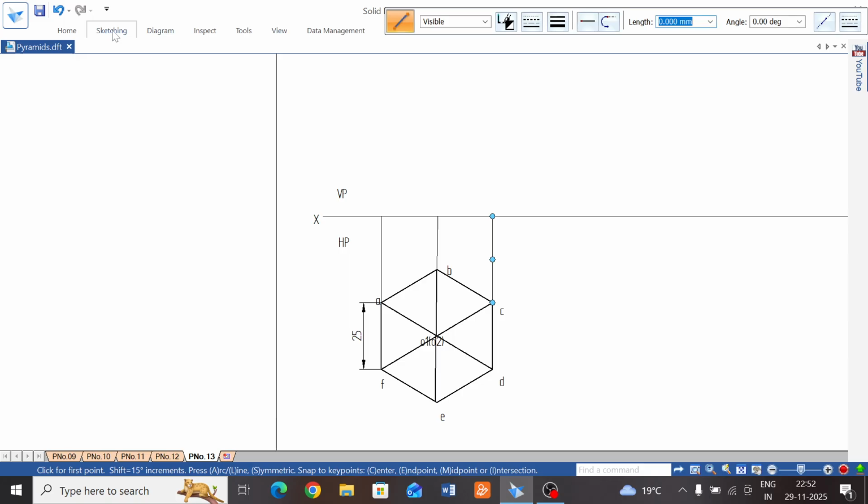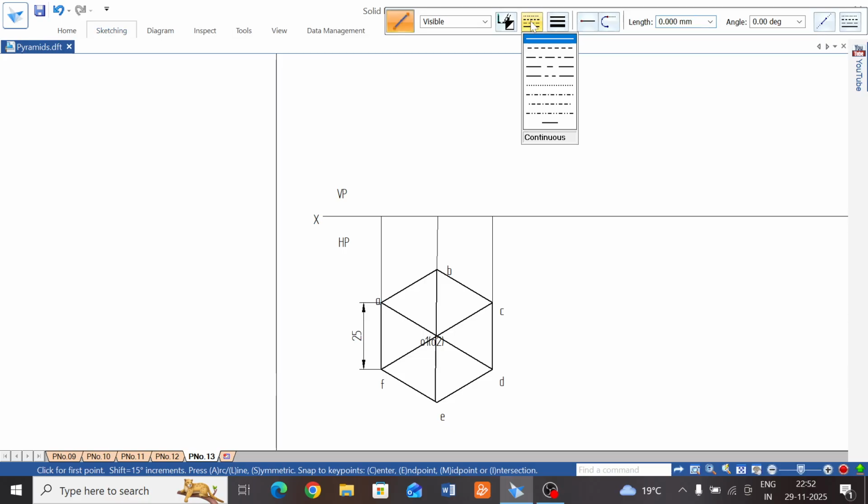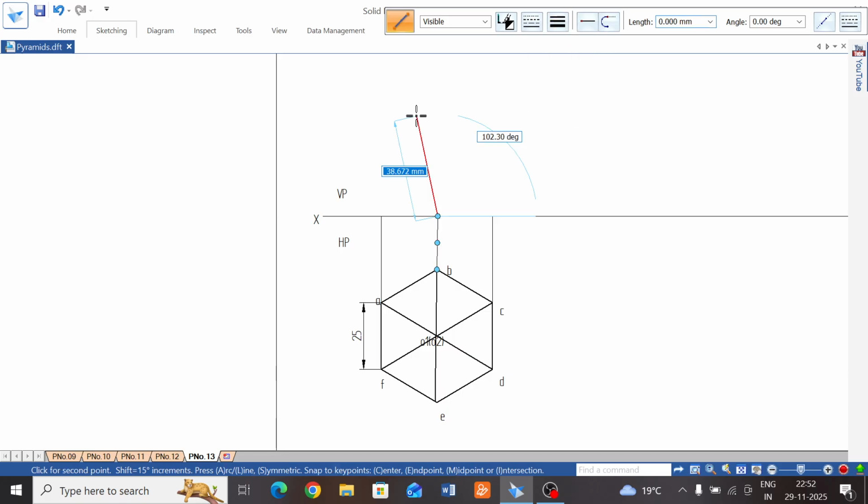Okay, next go to line, the axis line, you select the axis because the edge is there. In edge case, the axis won't be visible because the edge is coming in front, and need not select the axis line, directly select the thick line only. From this point, to project the axis, pyramid height is given, axis length is 50 mm, type 50 and 90 degree.